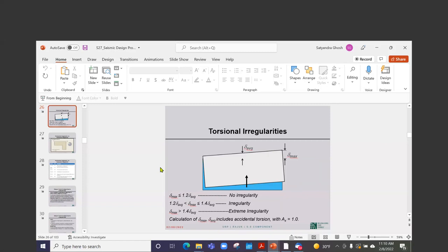From the definition of soft story and weak story, we know what they are, but you didn't tell us how to evaluate them. You did. Dr. Ghosh went over it. I don't know what you mean by evaluate. I specifically said strength is the shear carried by the lateral force resisting element, and the stiffness is the reciprocal of deflection.